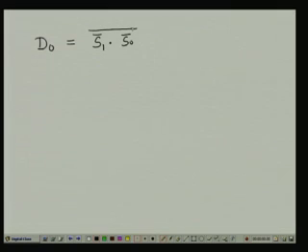For the active high decoder, the case we considered last, for D0 the term was S1 bar S0 bar. So, it is the complement of S1 bar dot S0 bar, which is nothing but S1 plus S0, that means the OR.